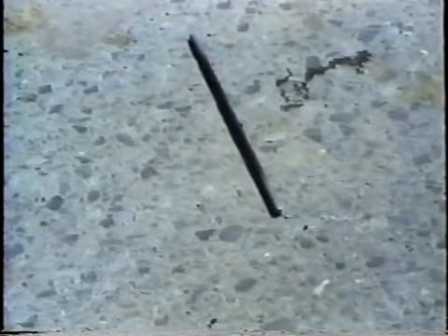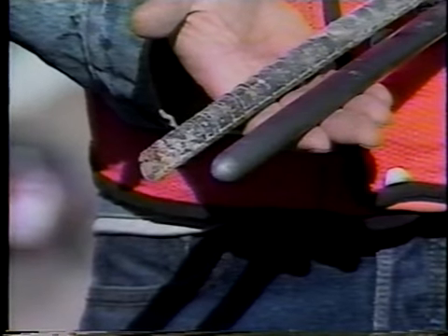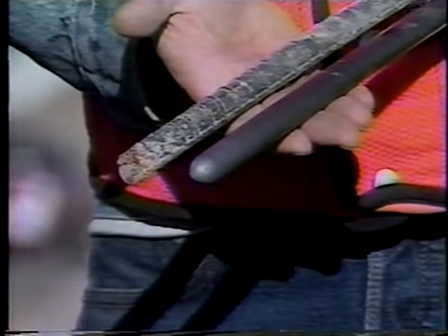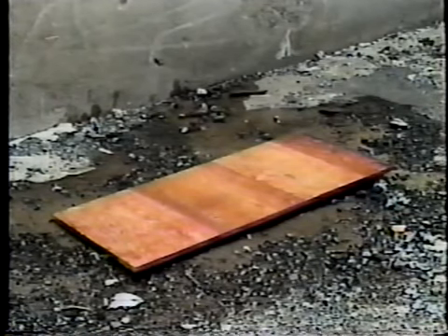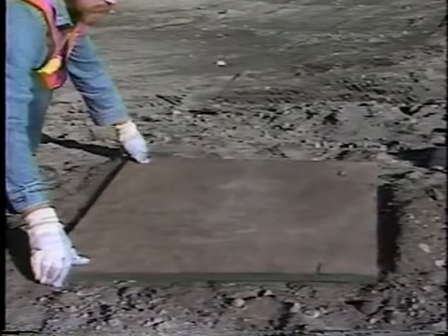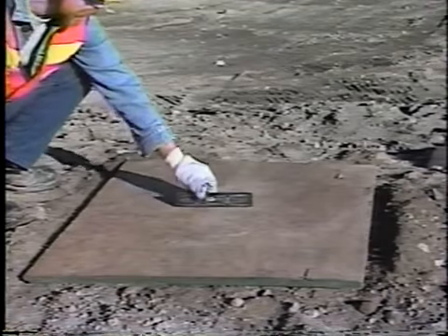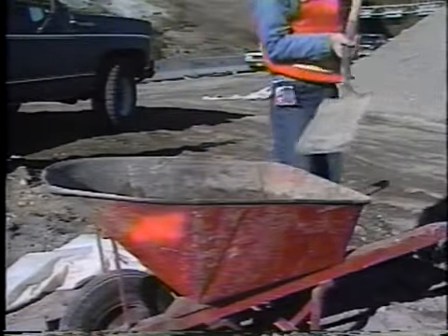A standard tamping rod is smooth with a rounded tip. Makeshift rods, such as cut-off reinforcing bar, are unacceptable. The base for the cone must be strong, rigid, and stable enough to support the tester as well as the concrete and equipment. It needs to be level and firmly supported so that it won't rock or bounce. The sample should be brought close to the test location and remixed if necessary until it looks uniform.